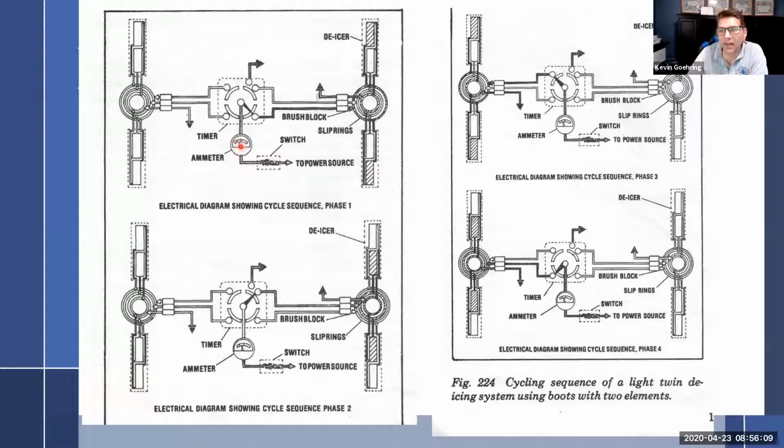Now here's the thing about that. That's great for the pilot, but as a mechanic, we have to check these things on an annual inspection. And this is where things go bad. The way we always did it is we used two guys. One guy got in the cockpit, turned on the master, turned on the prop de-icers, and another guy stood out front and would feel the prop and call it out. Prop outer, inner, outer, inner, got it, turn it off.